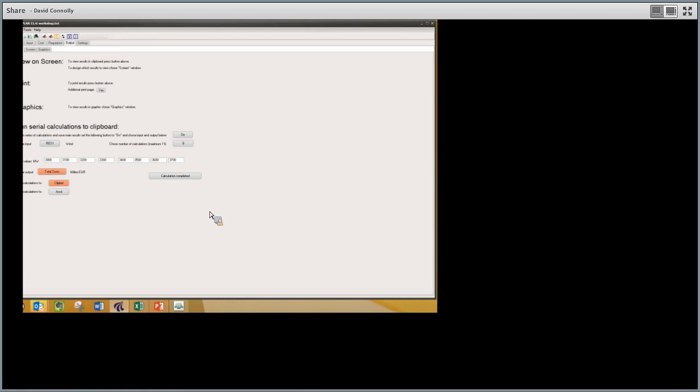was just looking at the optimum from a total cost point of view, but you could also use it for a variety of other different metrics. And these are all listed here. The ones that I'll just highlight are, for example, fuel total. So you could identify what the fuel consumption is for lots of different wind power capacities. So perhaps the optimum wind power is the one that requires the least amount of fuel in the system. And the other one I will highlight is CO2 emissions, for example. That could be another way that you want to identify the optimum level.